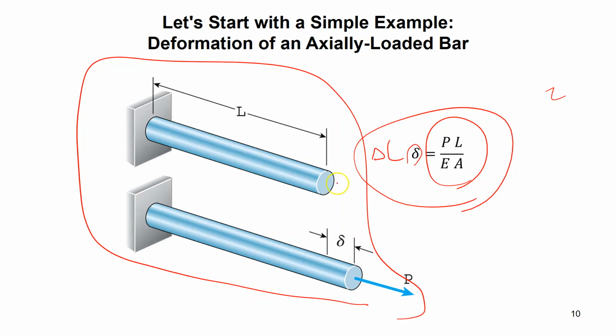If now you apply a tangent force instead of a tensile force, then the behavior will be different. You're going to see bending. And if this part is now different and it's not a simple rod, it's like an L-shaped rod like this, and you apply a force at an angle, which has both a bending effect and a tension effect and then shear stress and so on, you're going to learn that in ES202. It's called combined loading, and that is much more complicated.